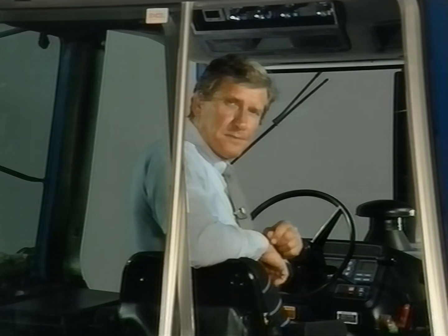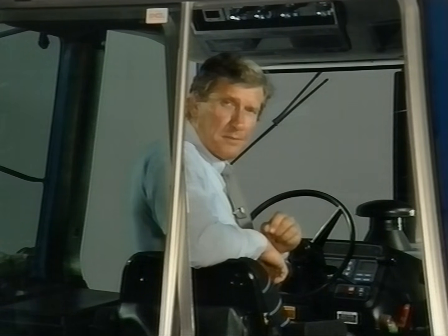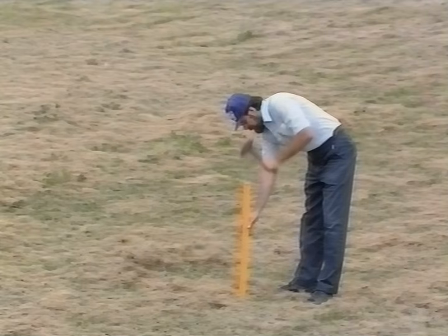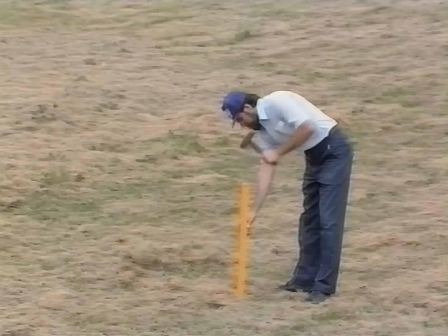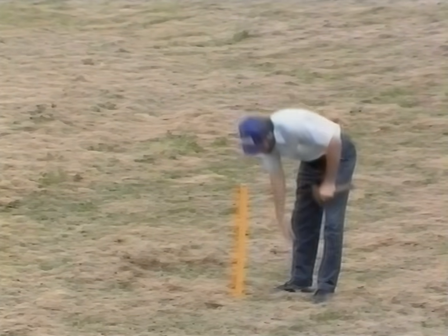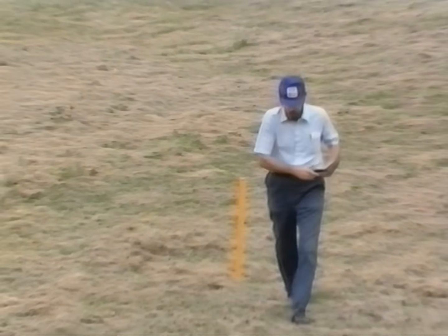In this function, the monitor uses a measured distance to match the calibration of the console to the readings from the radar ground speed sensor. This is similar to measuring the rolling radius of the tire and entering a calibration number in the EIP when a tractor is not equipped with a TPM. The measured distance is 400 feet, and it should occur on a course that runs over hard, level ground.